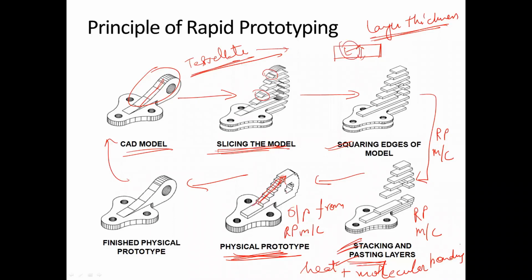This layer thickness has to be minimized. The staircasing effect is not being generated due to mathematical information. It is being developed due to this layering process. So the most primary parameter of the layering process is T, that is layer thickness.